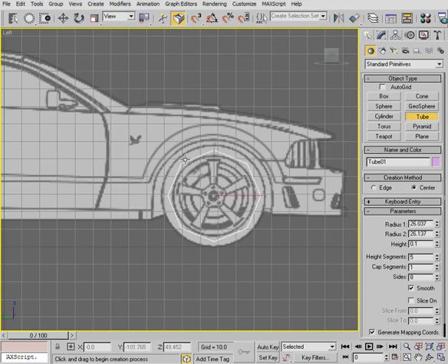So I'll go ahead and pull that out, just out to that outer edge, and then for that second radius, I'll go ahead and pull into where that opening starts, and then I'll just give it some height. Doesn't really matter what the height is. Now, right off the bat, I can see that this is very low res. It's in fact too low res for what we need to do. Since the computer's doing the work for us and it's going to create this nice curve, we might as well add some extra res because we know we're going to eventually need it. So let's go ahead and up this res to, let's try 16. We could try 18. I'm going to go ahead and set that up to 20.